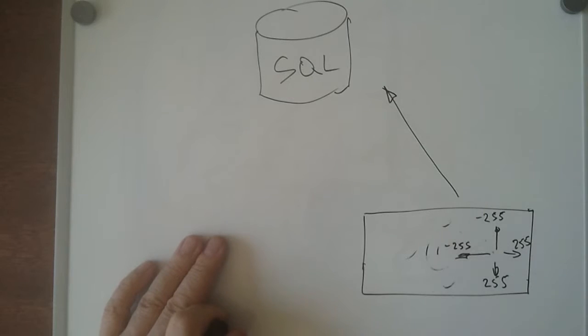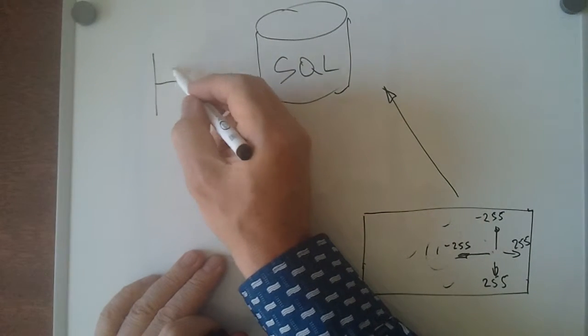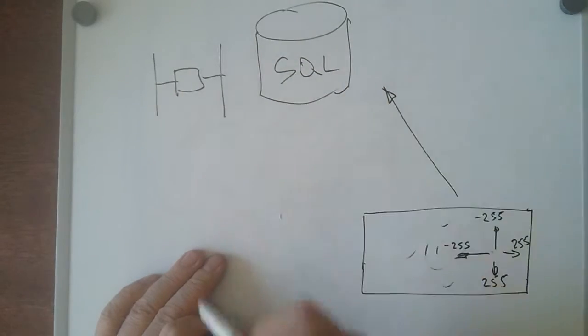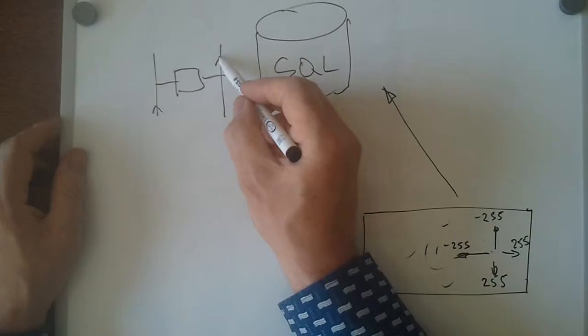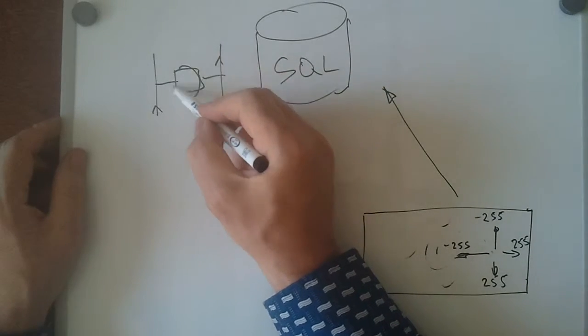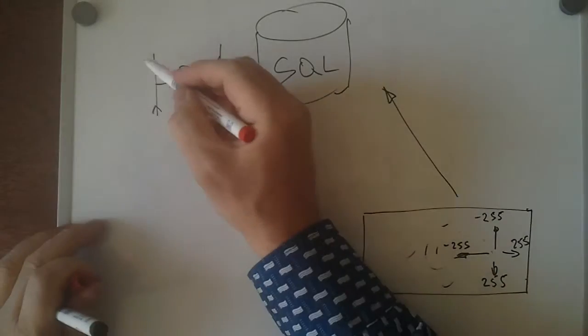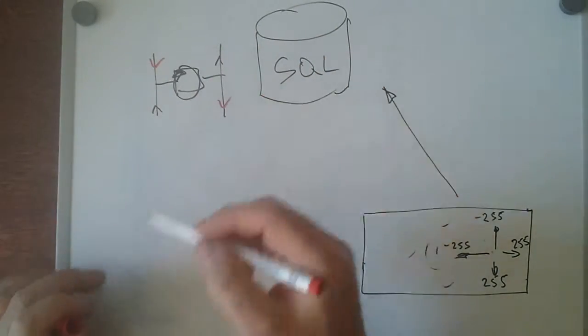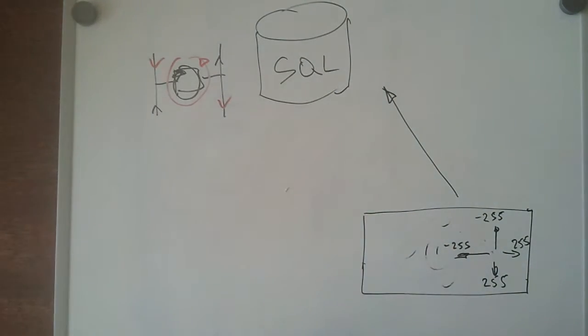I've got one of these H controllers, so the way they work is you put a motor just there. If you drive current this way and out that way, the motor will spin in that direction, and if you drive current this way and that way, then the motor will spin in the other direction to the one I just drew, whichever one that was.